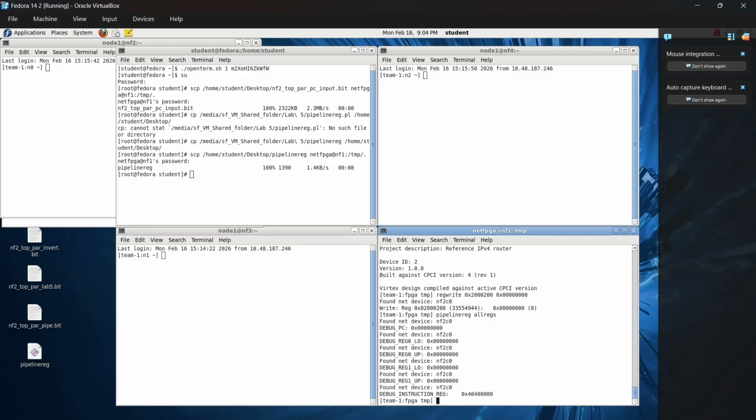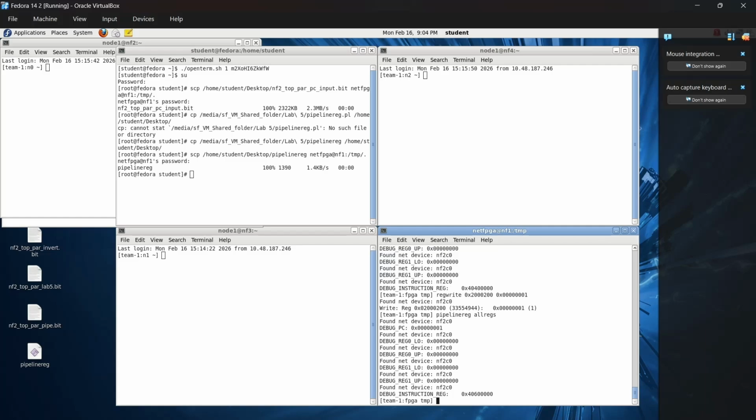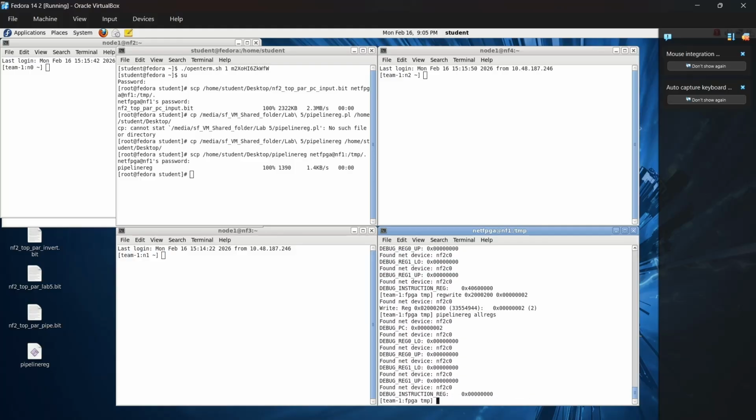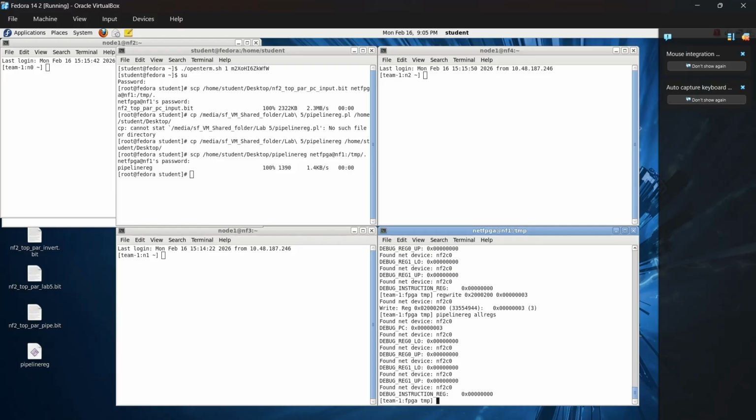So with PC equal to 1, the instruction will be this value, and the IMM will also be given as zeros, the entry is going to be all zeros. It's working now. Let's increment the PC and see. So yeah, 406, which is the second value, I think, which matches with us. For 2, it's a no op condition again, matching with the value we need. And 3, again a no op. There'll be 3 no ops, so that's the second no op.